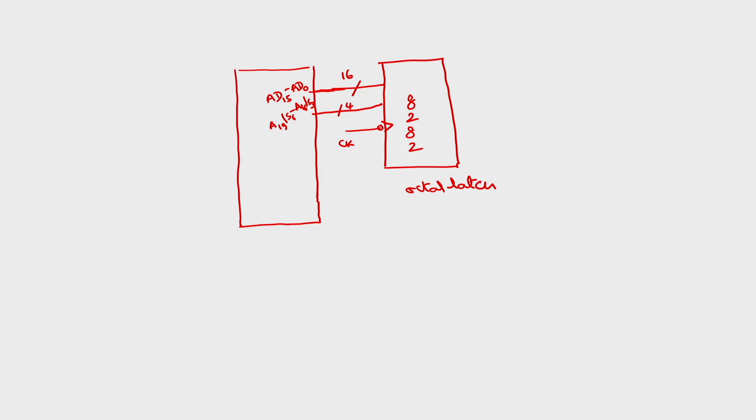So, there are totally 20 different signals from the 8086. One signal we have to connect to the one input of each D flip flop, that is the configuration here. Then this clock will be applied to a signal called address latch enable.